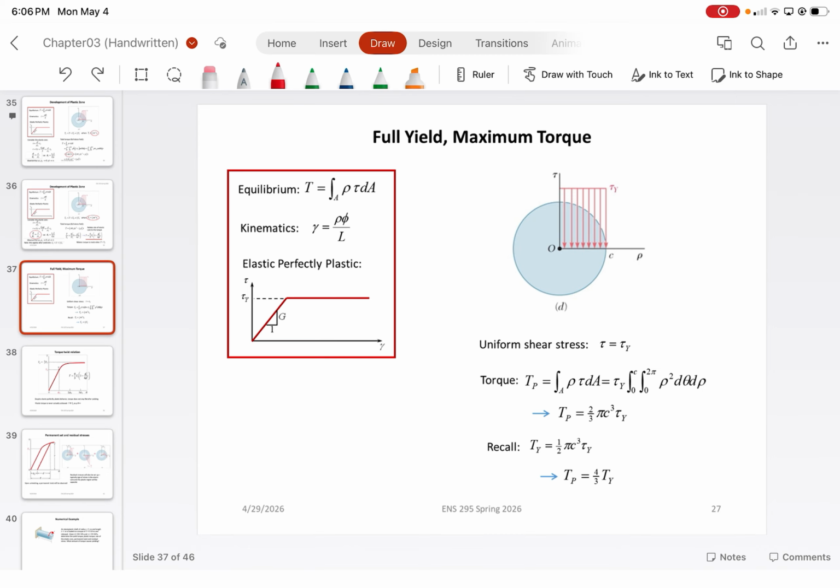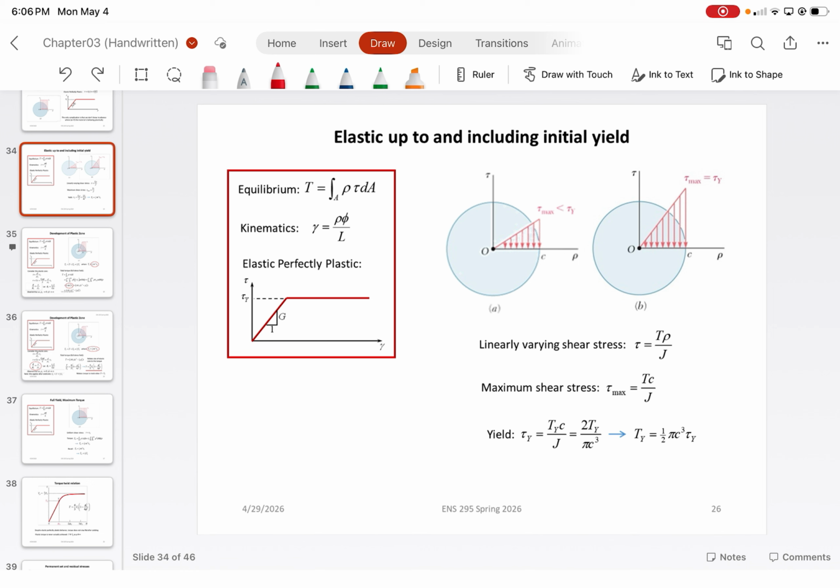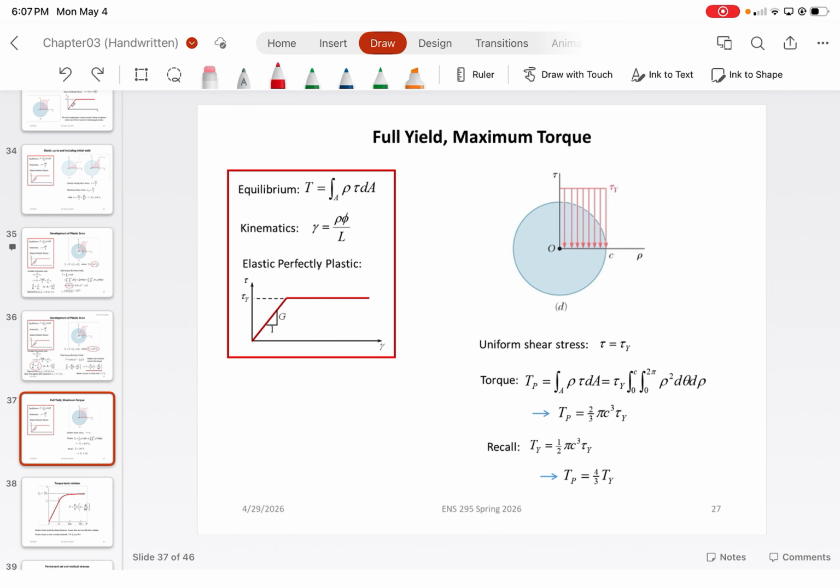Right, the plastic section modulus and elastic section modulus. You would be able to derive similar terms, but in this case, because you're dealing with a circular shaft with a very simplified geometry, we would just find that the total plastic torque, or total plastic capacity, would just equal 4/3 times the yield torque, where Ty would be the triangular stress distribution that we had previously assumed here, assuming a linear elastic region. So the ratio between that rectangular torque and the triangular torque is just a matter of 4/3.